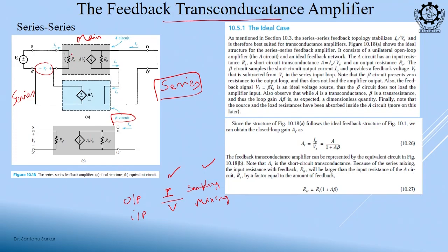Input amplifier should have a input resistance, that could be infinite, but for the moment we are drawing that, okay. It should have a voltage gain, it should have a output resistance. Now, as this output side is in current, we draw this is in parallel, okay. We draw that amplifier like an current amplifier, okay. Now, in the feedback circuit, input impedance we are not considering, and we are just considering a beta gain factor, only a gain factor.